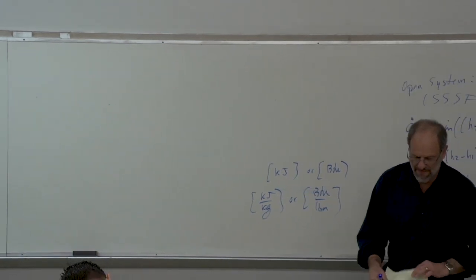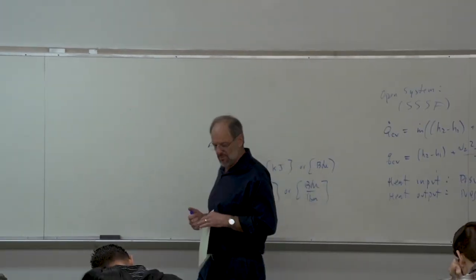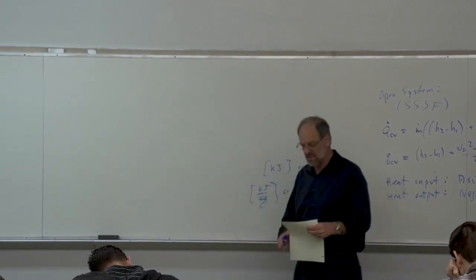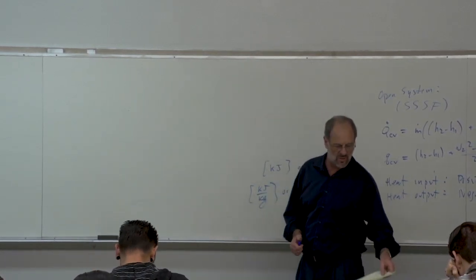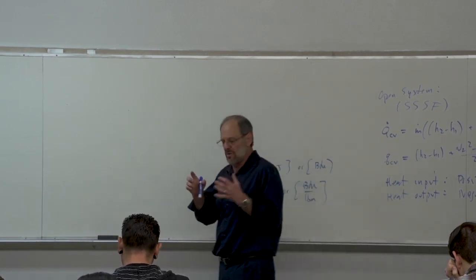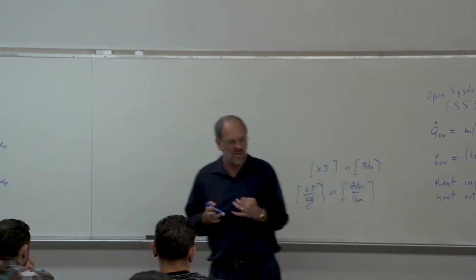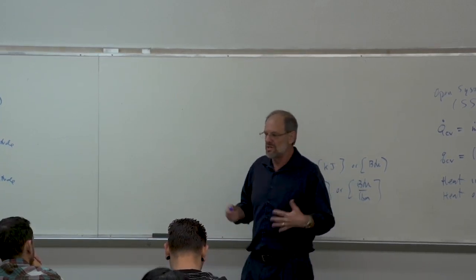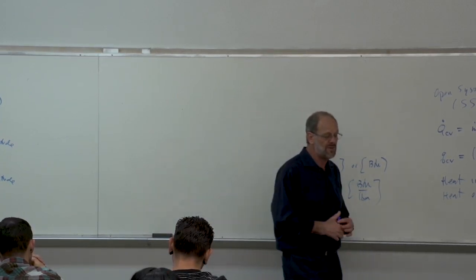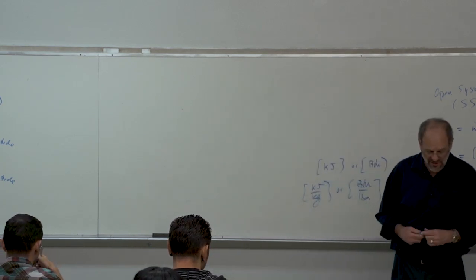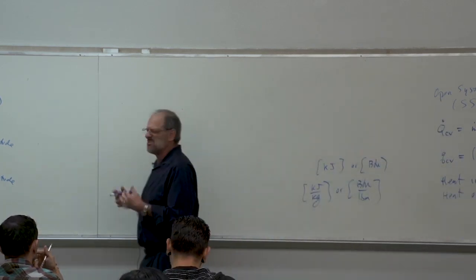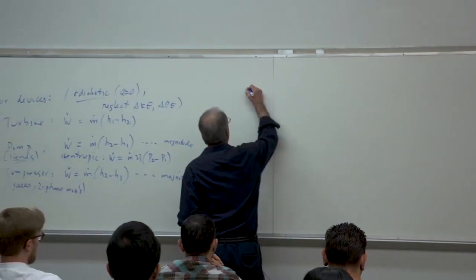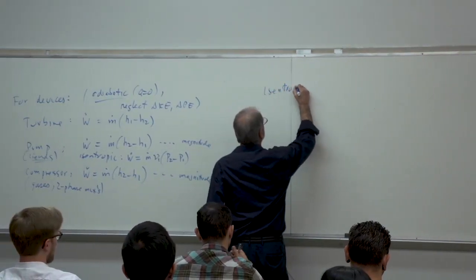So, moving ahead then, when we analyze a typical pump, turbine, or compressor, these particular single stream steady flow devices, what we often do is want to know how the device performs compared to an ideal pump, turbine, or compressor. Okay? And for those situations, we define what's called the isentropic efficiency. So isentropic efficiencies sometimes can be called adiabatic efficiencies. It just depends on where you're looking. But let's talk about isentropic efficiencies.